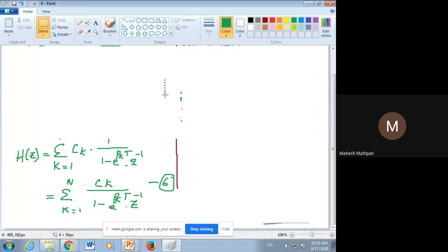Yes, sir. Of equation 6. So therefore, what we are writing is here. First thing is, we are writing the analog form. It is like analog is what? 1 divided by S minus PK is the analog term. Okay. So if I want to convert it into the digital form, what I am writing is 1 divided by 1 minus e power PK T into Z inverse. So this is the relation we are finding while converting analog to digital form.